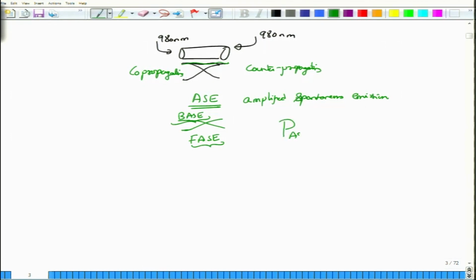If you look at the average power because of the ASE spread out over the band that we were looking at, the average power depends on the spectral density of the ASE noise, which is quite flat and has a range which is quite wide. It can cover all the way from 1500 to about 1560 nanometer, which is the range we are normally interested in. Of course, you do not really use the entire range for a given channel. Each channel will have a certain band, as we have talked about in the previous module.